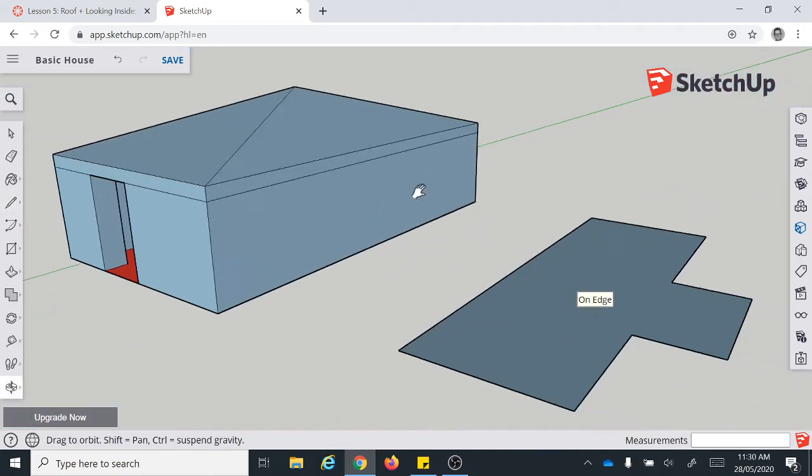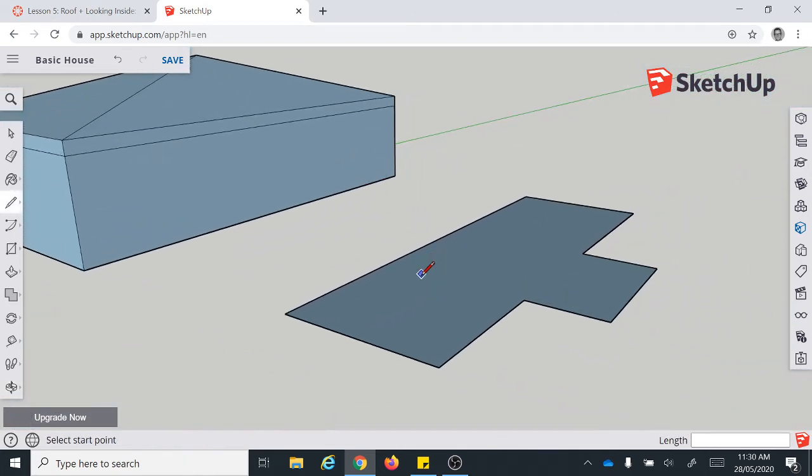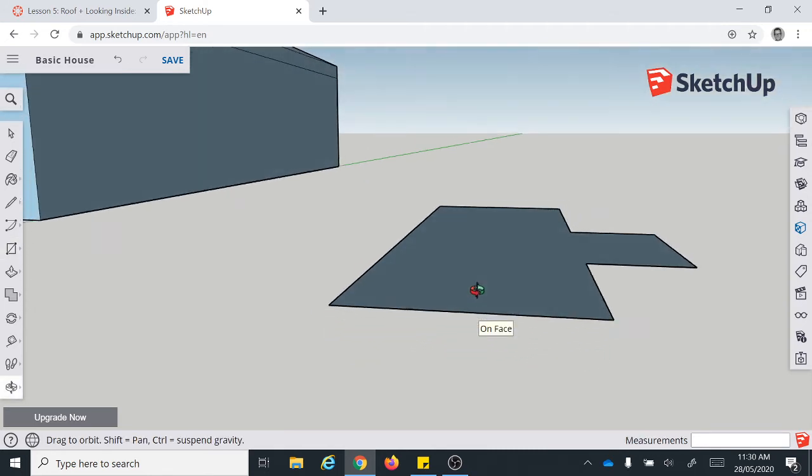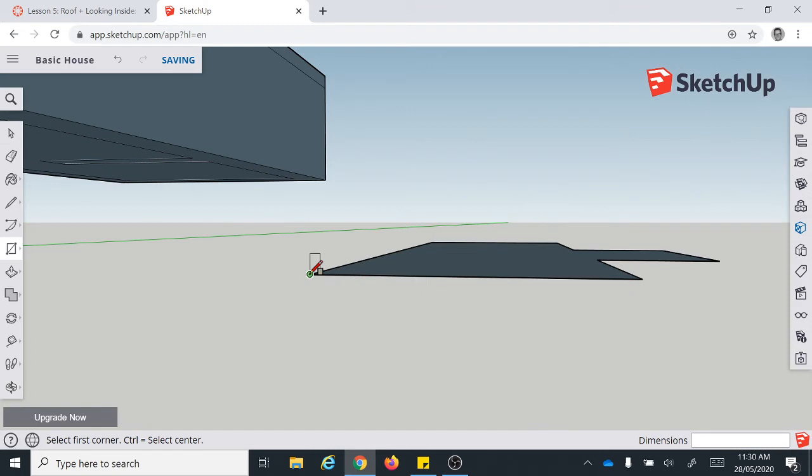We're now going to look over on this T-shaped one, and I'll show you a different way to do it. And there are other ways you can do roofs, but these are just a couple of techniques that are useful. So in this situation, I'm not going to start off with my pen tool. I'm going to start off with my rectangle, and I want a rectangle that's sticking straight up from this edge. So I'm going to angle my camera so I'm looking at it from the edge, and I want it to be exactly here.